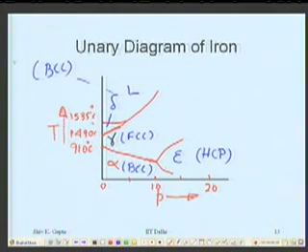Two variables, both pressure and temperature, can be changed in the area to remain in equilibrium. And we can also see that two-phase equilibrium exists along these lines. Along this line exists equilibrium between gamma and alpha. Along this line exists equilibrium between gamma and epsilon. And along this one, two-phase equilibrium only between alpha and epsilon.